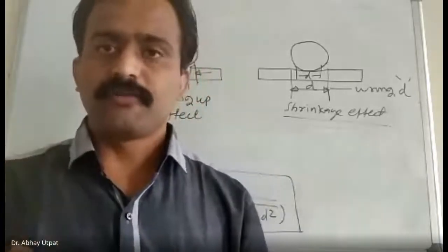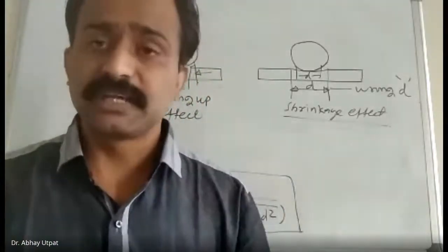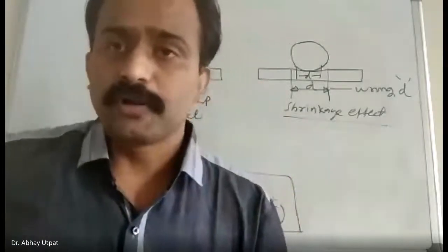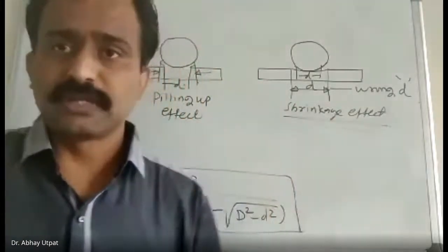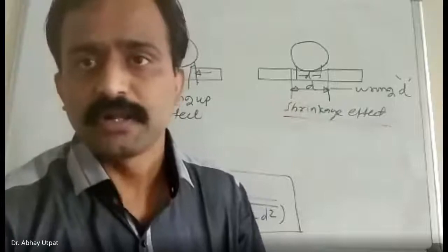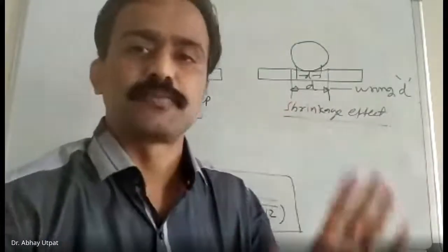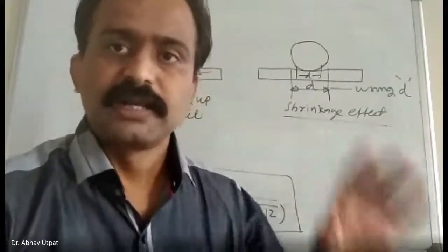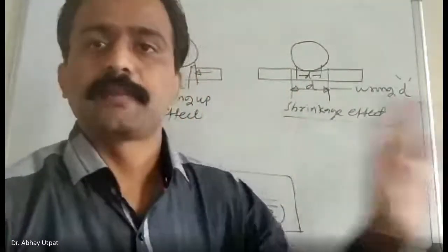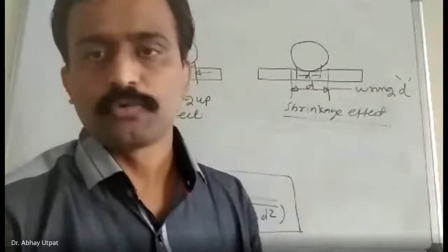What is the load for Brinell hardness test? 3000 kg for ferrous, 500 for non-ferrous. And the indenter is a ball indenter, 10 mm size. I repeat, 3000 kg load and 10 mm. Load and indenter, you have to remember.